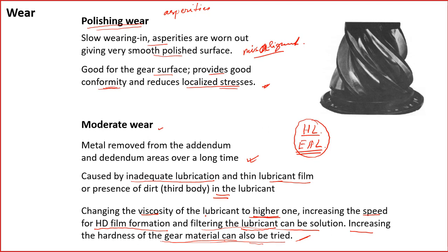So depending upon the severity of our stress and speed, we have to find a solution. If the stress and speeds are not that high, then perhaps just grease can help for long-term application. But if the speed is very high and stress is very high, that will lead to high temperature as well. If temperature is also high, then we need to have a proper solution for lubrication, as well as start with a hard material for the gear.